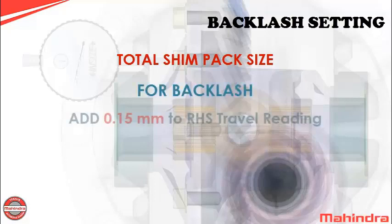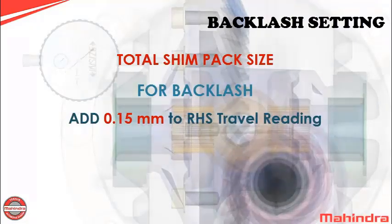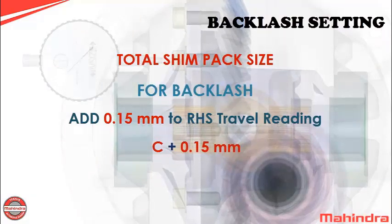Now we can calculate total shim pack size required for a backlash setting. We need to add or remove constant values for backlash and preloading from the final shim pack size. For backlash, add 0.15 mm to the right hand side travel reading, C plus 0.15 mm.